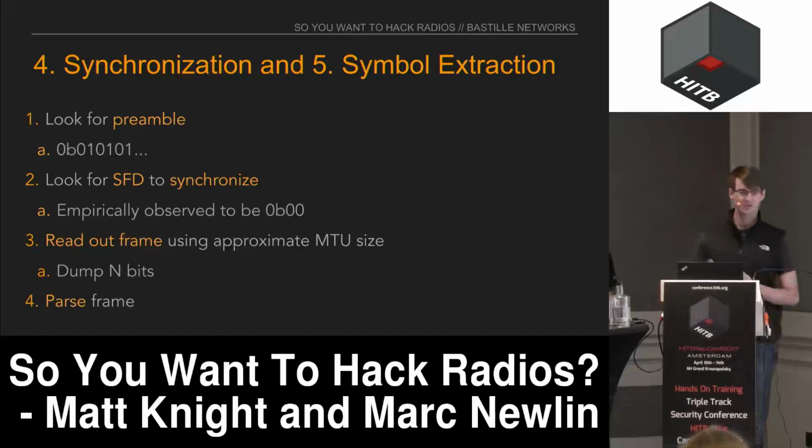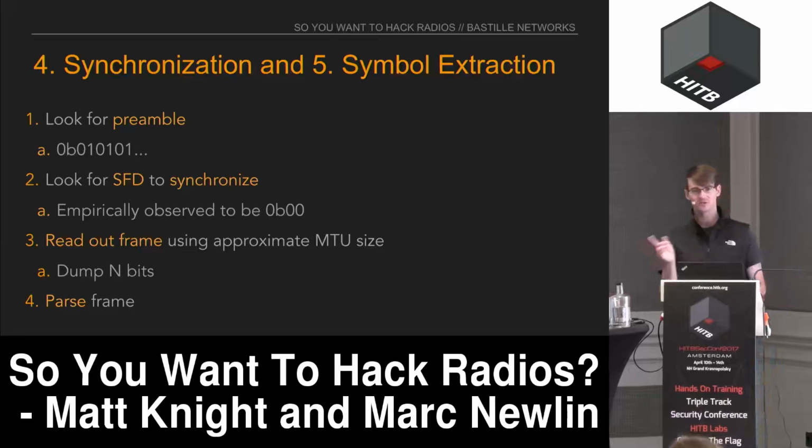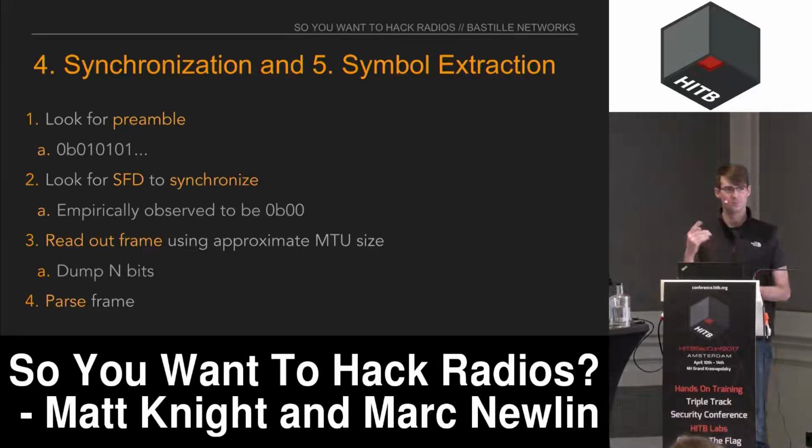Really what it's doing is looking at the stream of ones and zeros coming in from the GNU Radio flow graph, and it's looking for the preamble. The preamble is going to be that alternating sequence of one-valued and zero-valued samples, right? Because with FSK, the preamble we expect is going to jump back and forth between the two frequencies, just as we saw in the interactive example.